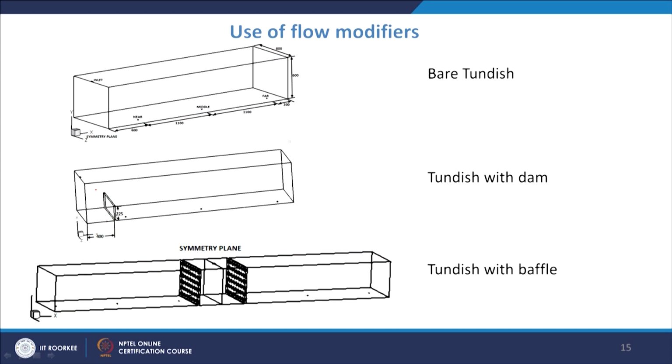So, the idea is that you can very well see the velocity vector and you can draw the thermal contours. You can also draw the contours for the turbulent kinetic energy, which will be indicative of the value of these parameters, turbulent kinetic energy, where it is higher. So, where you have the velocity higher, you will see that those values will be more.